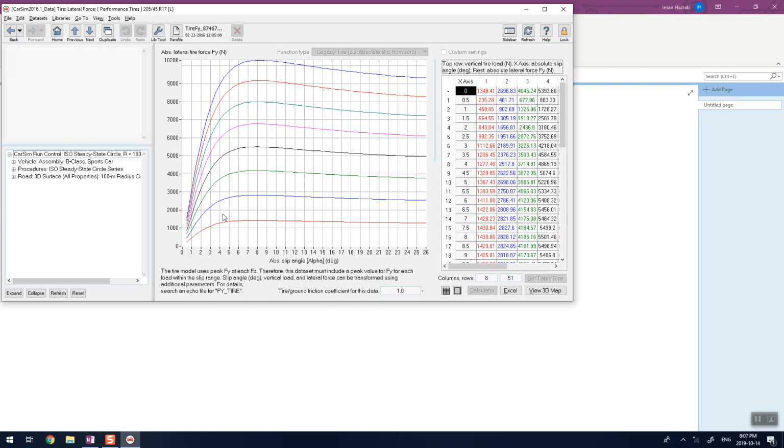If you click on it, it's a tire, 205 R17, the way you read regular tire size. Export it to Excel because I want you to try to use the result of the software, this graph and the load distribution, to find the C alpha and K understeer of the vehicle, as a validation or better understanding of the model.